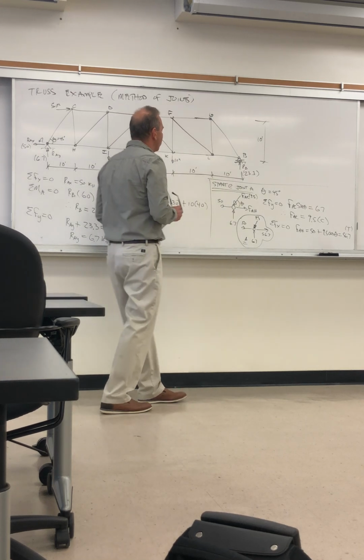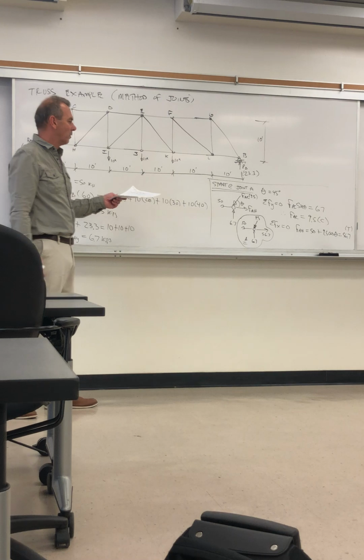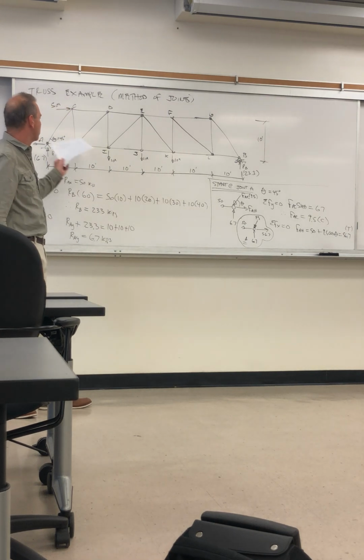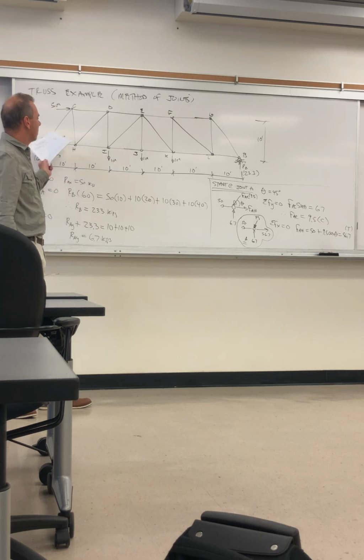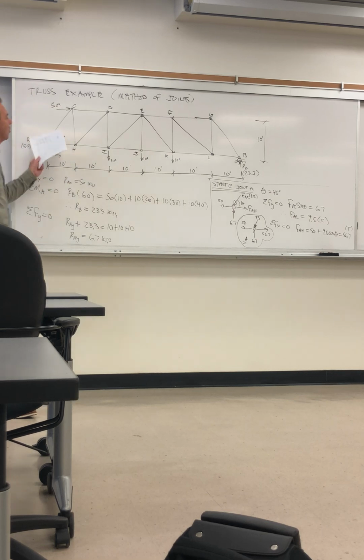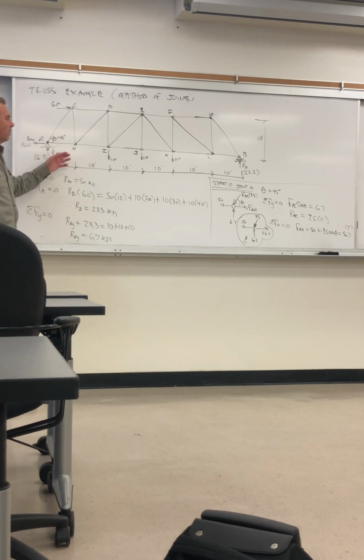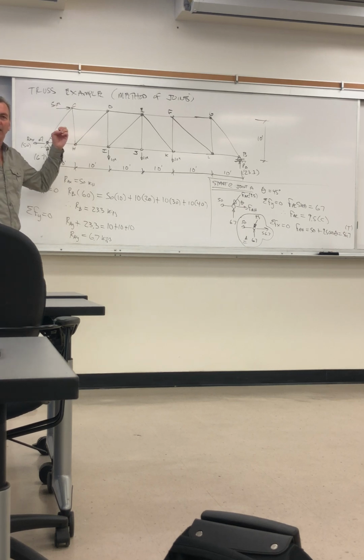Yeah. And then the last step you do before you move on is you draw all those forces here, the ones that you just found. Otherwise, it's not obvious where we're going next. So if we try to start at joint C or H, let's say we wanted, before we did A, let's say we tried to go to H. There are 1, 2, 3, 4 unknown forces, right? And we have at that joint only 2 equations. So we wouldn't get a solve for those forces.